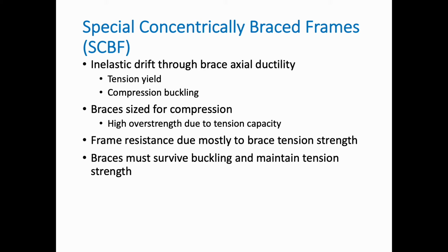So what we want to achieve, in fact, is to get the buckling of the braces, but that buckling does not reduce the tensile capacity of the members when the load is reversed and now the braces are in tension. So although the braces will be loaded in compression, and they will form a plastic hinge, what we don't want is to get to an instability point where the system will not be stable any further.